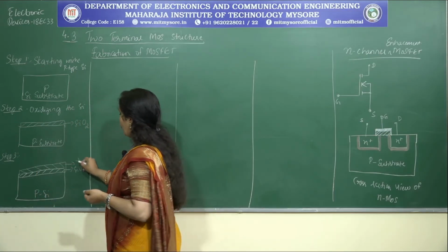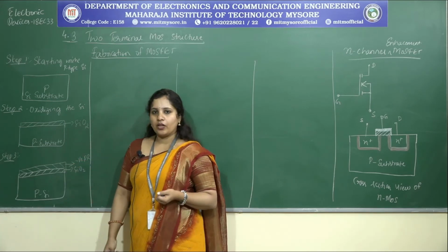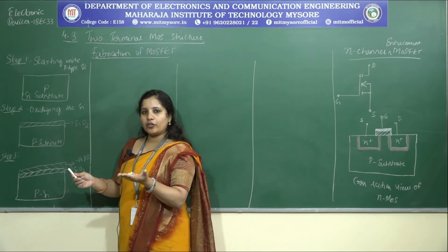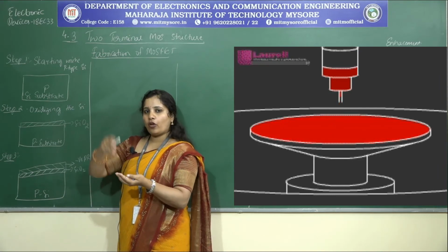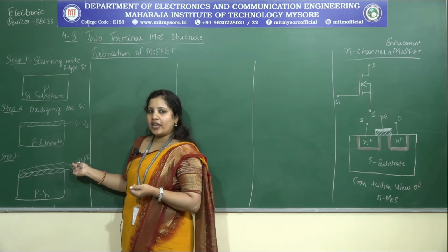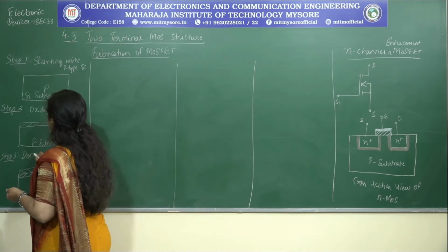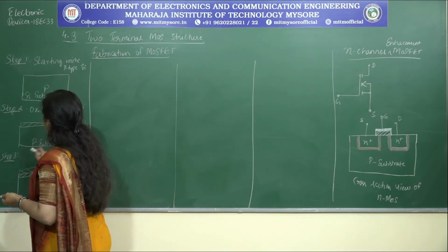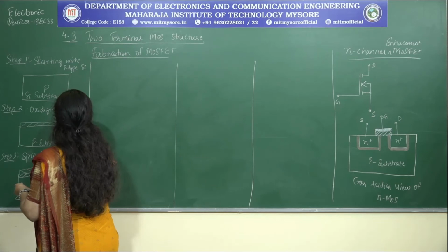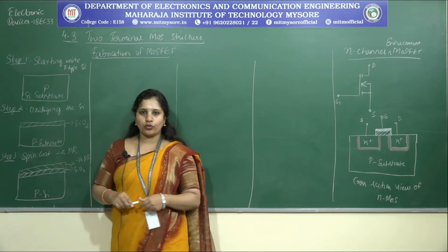Here, let me consider the photoresist to be a negative photoresist. I have formed a silicon dioxide, and then I keep it on an instrument in such a way that it will spin, upon which I deposit the photoresist. And the kind of photoresist material I have used is a negative photoresist. Therefore, step number 3 is to spin coat negative photoresist. Done. Therefore, I have spin coated with a negative photoresist.